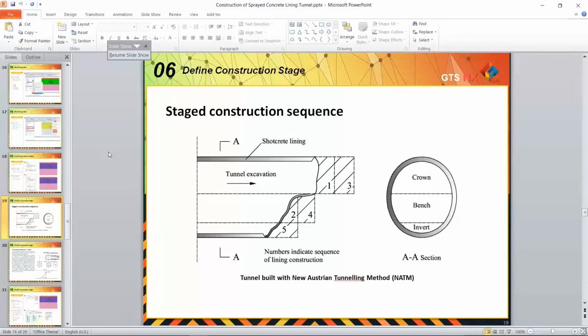The stability of the tunnel crown depends on the geometrical setup of the tunnel, such as vertical depth, height, and width of the tunnel, and the material properties of the shotcrete lining and the medium. Assuring the stability of the crown is essential for the safety of the tunnel structure as well as the structures nearby, if required.